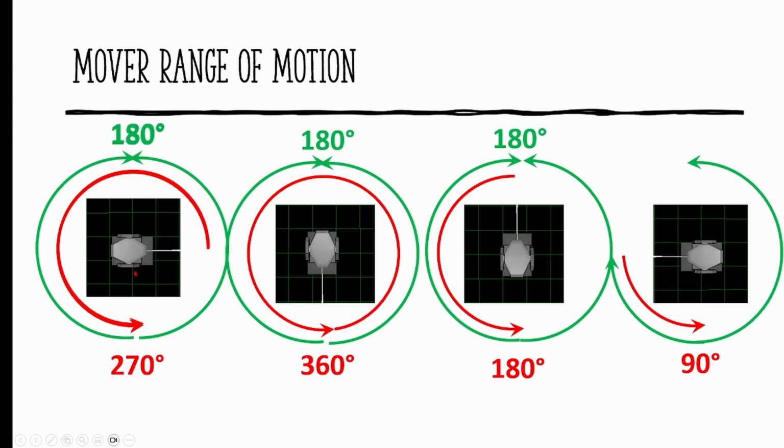So that's 270 degrees. Now remember, we said we can do 540, so I could still go 360 and around even to 540. But now what I've got is I can move that moving head. I can go this way 180 degrees and this way 180 degrees, and it's all within the motion of the moving head. Okay, and that's the key. When we're setting up the movement of the moving head, we want to be able to move the moving head in either direction from the show center, so that when we utilize it, we can put the light where we want it.